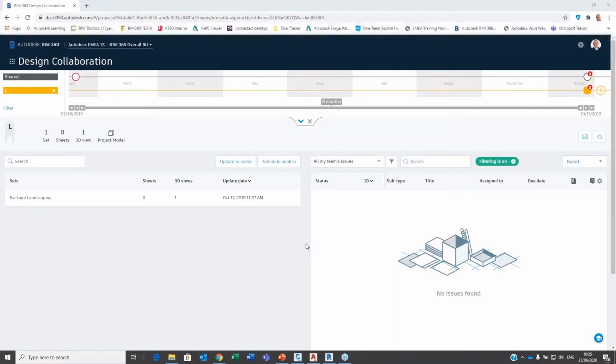So what am I talking about? Well, before I dive into Civil and before I dive into Plant, obviously those are based on AutoCAD. If I have my whole Civil 3D project and I just want to export a DTM object, a digital terrain model, as a simple DWG file, then I can do that again with BIM 360 Docs. Okay. If I want to use data shortcuts on Civil 3D, if I want to use the database structure of Plant 3D, that's where you need a BIM 360 design entitlement.